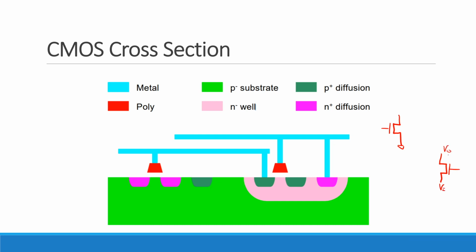If I just typed this into SPICE, I'll give these things all labels. I'll call these A, B, C. These are all just the nodes that I've labeled there. So I type this into SPICE and try to simulate that circuit. Assuming A, B, C, and VI and VO are all independent of each other, is there any connection between those two transistors, or are they totally independent of each other? Again, in SPICE. Yeah, in SPICE, they're basically independent.